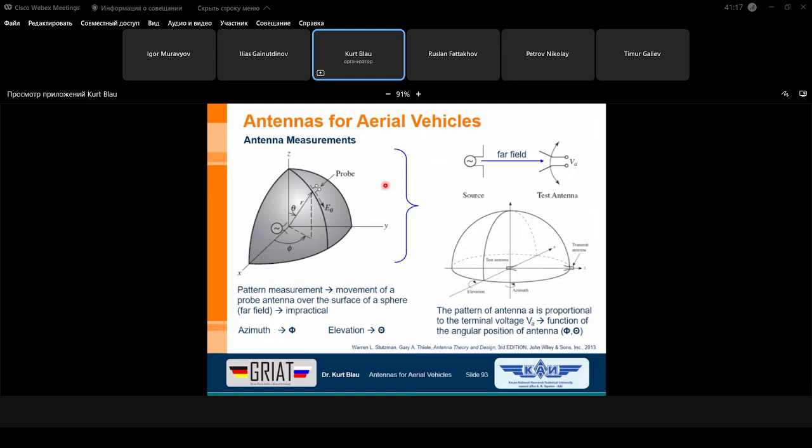Yeah, and if the wavelength is, for instance, very large, then it's clear that because of the large wavelength, your measurement distance is also very large, and so you have to hold this distance, let's say 2 wavelengths or 3 wavelengths in case of a wire antenna, and then the problems are starting, because you also have to go up in height, and then you have to realize the measurement condition.